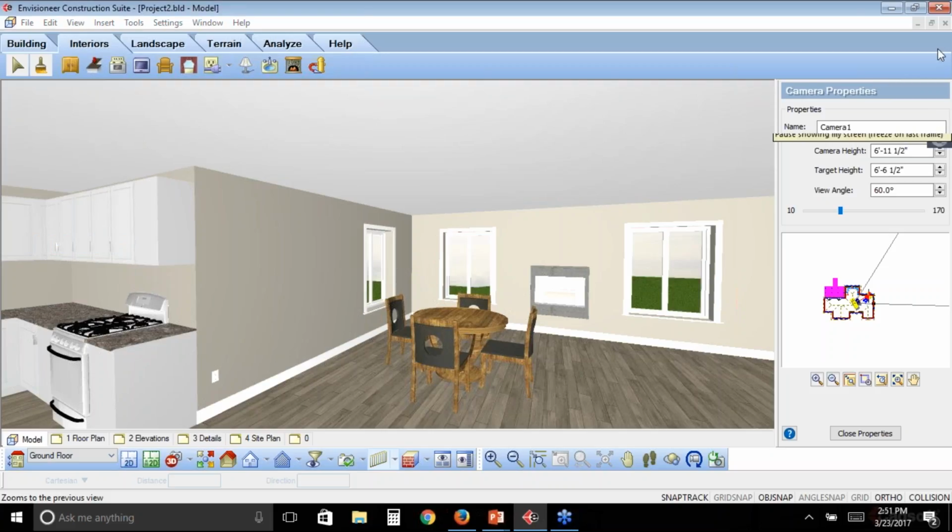Okay, looking at my next question. How long does it take to render your model from your software into an HTC Vive or Oculus? That's instantaneous. So if I went up to view and went into that presentation mode, if I had an Oculus Rift or an HTC Vive unit attached to my computer, it would instantly, when you pick on the VR mode button, go into that environment and you're navigating right away. So it's not taking the moment to render as you go. You set up scene properties before you even get there to tell it where you are in the world, what time of day it is, and it'll cast down shades and shadows for you.